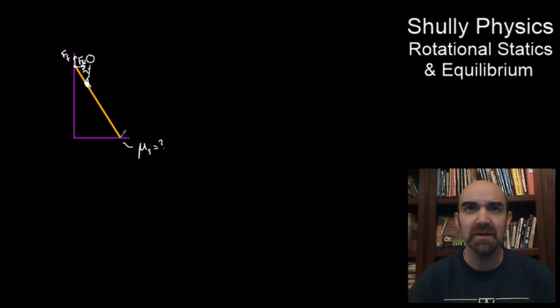Down here, the tendency of the ladder at the bottom is to slide out this way if there were no friction. So there's some friction holding in this direction, and also some normal force. Now, are those two normal forces equal? No, they're not going to be. So this is from the floor, this is from the wall up here, and those are the two forces. Those two contact forces are what's holding on to them. Collectively, a couple of normal forces and a couple of frictions.